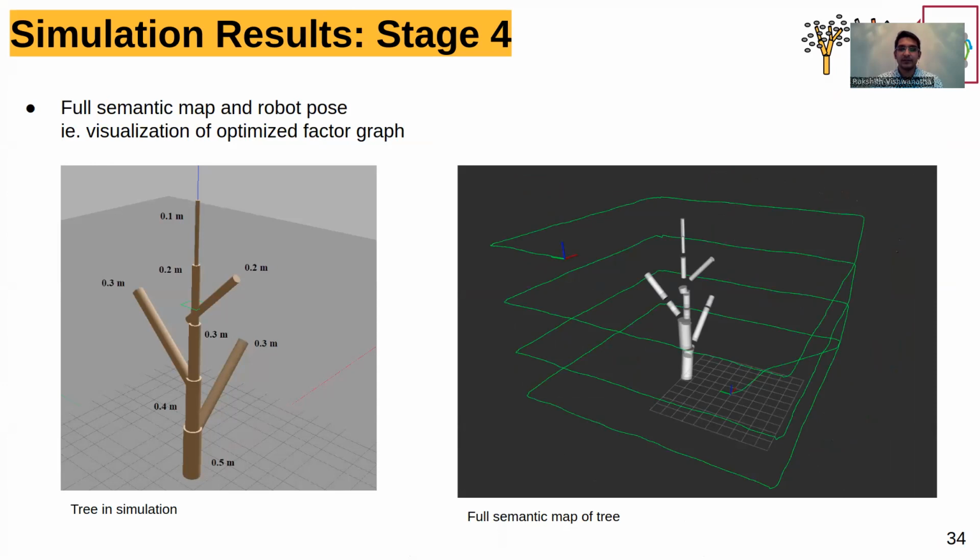Right. So in terms of performing this offline, part of it is correct and part of it is also still real time. When I ran my algorithm, I didn't run it on the sensor suite itself, but instead I ran it on my laptop. The algorithm was run using ROS bags, so recorded data which was played back in real time. The configuration of my laptop was quite similar to that of an Intel NUC, with 16 GB of RAM and an i7. So while running continuous streams of data, it was able to build this map as data was incoming.